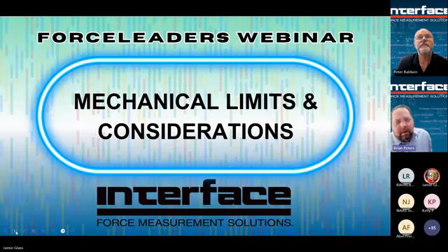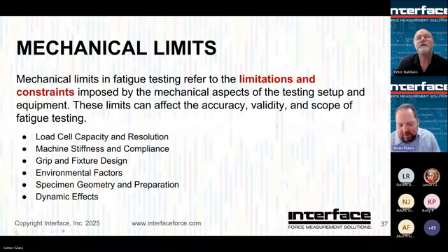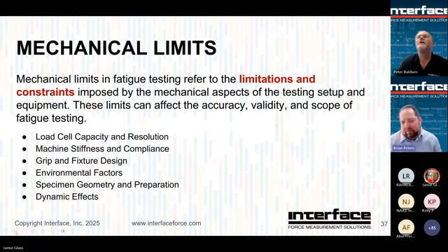All right, thanks, Peter. All right, so we talked earlier that the strain gauge itself has pretty negligible influence, even in high cycle. The bridge response is going to be nearly instantaneous, and you're almost always going to be limited by the mechanical aspects of your load string or your entire test setup. So we talked a little bit about the natural frequency response, the stiffness of the load cell as being something you want to look at, make sure it's sized appropriately.